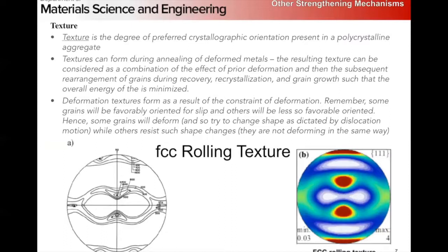Same thing from most solidification processes, right? If I just pour into a mold and then I cut a sample out from the center of that mold, right? We'll ignore edge effects, right? It's going to be large grained and fairly random, right? Because I'm nucleating grains in the liquid, and there's no preferred orientation unless there's like directional solidification or something. But there's no preferred orientation for how those grains are going to nucleate.